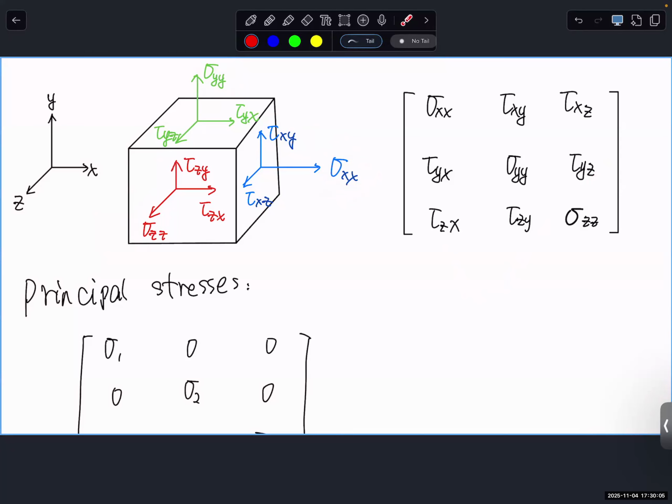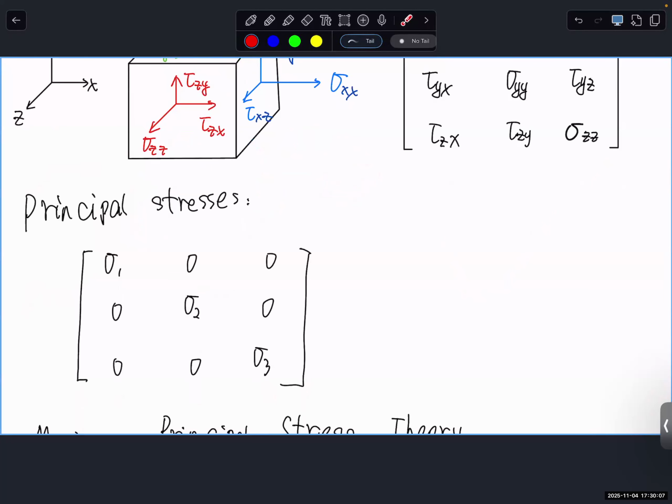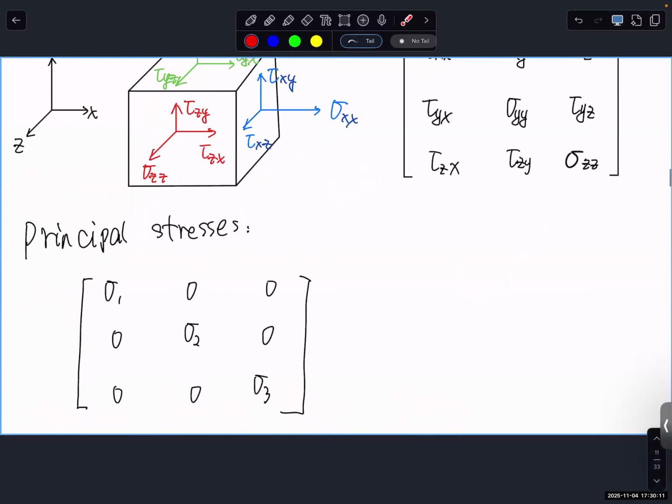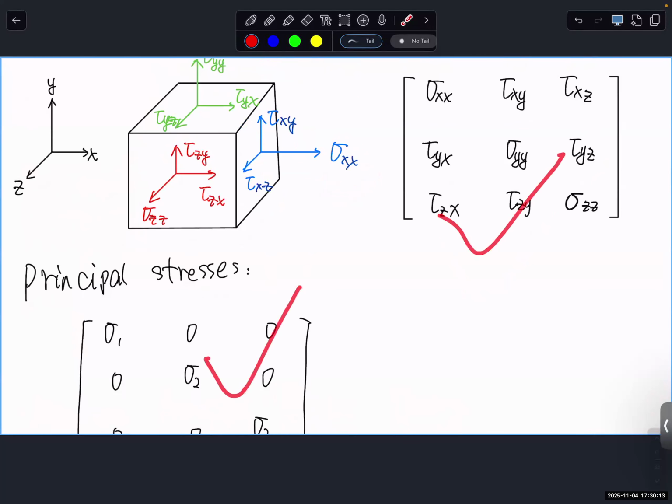And now it comes to the third principal stress: what does it really mean? So this is the state of stress based on the coordinates we define. We can calculate normal stress generated by tension compression, by bending, in the Y direction or in the Z direction, or shear stress caused by torsion, caused by transverse shear. We calculate all of them, and based on the coordinate system, we put them in the matrix.